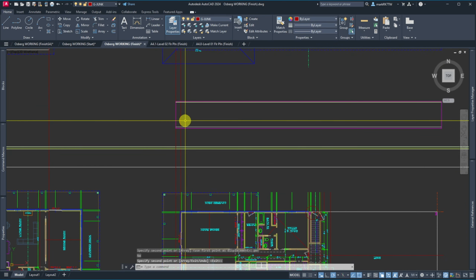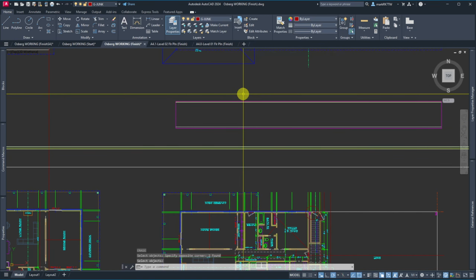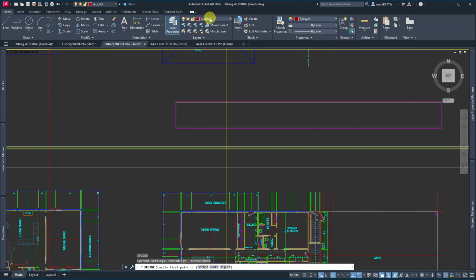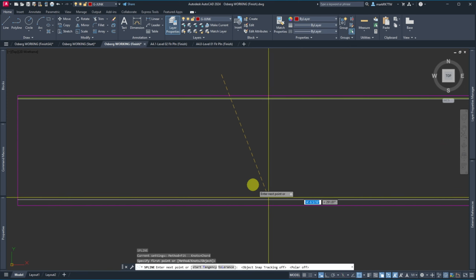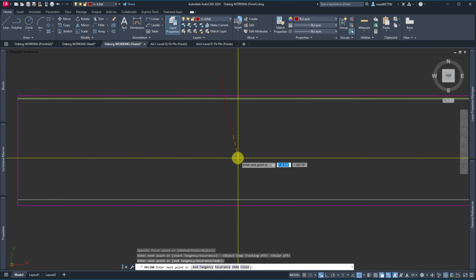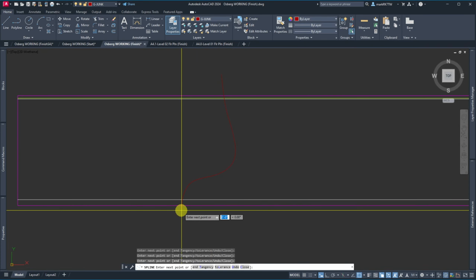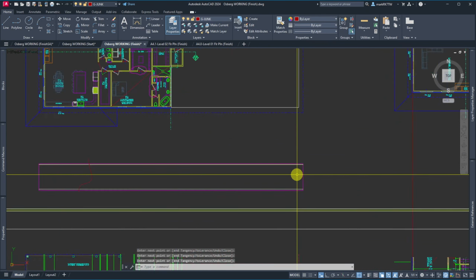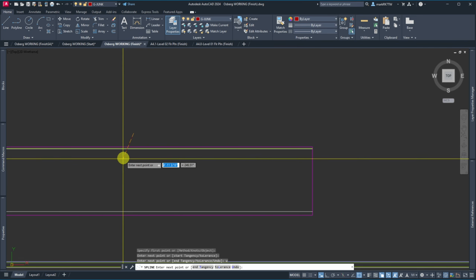I'll drop it here. Now that it's sitting in my elevation view, how I like to do stuff, especially on a big long building like this, is I'll put a spline on my junk layer. This is intentional to be on the junk. And this is why I turned these off the other day, is to do this. So now I've got pretty free motion in creating a nice free form through here that won't print. That's the important part about it. So I'm going to do the same thing here. Oops, I snapped to something.